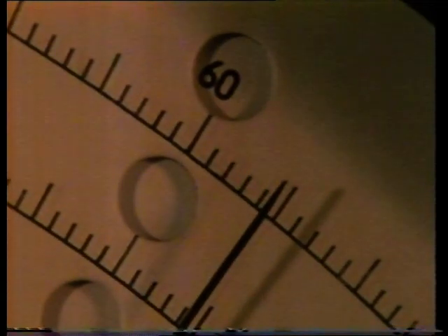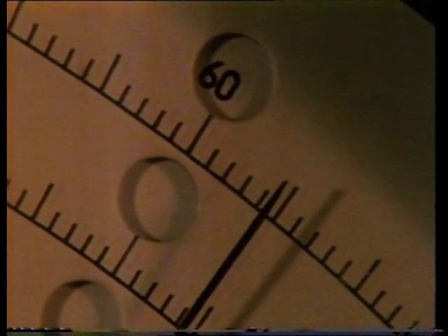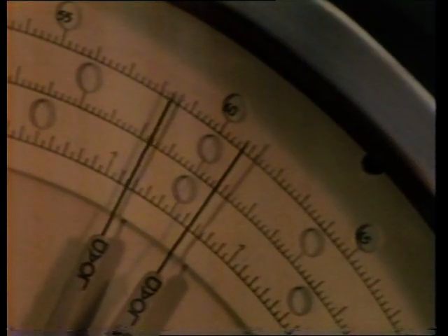Well, let's find out. What we're measuring here is the force required to pull apart a piece of 0.1% carbon steel. We're measuring the force in kilonewtons. That fractured at 61 kilonewtons. 0.25% carbon steel. Let's see what force is needed to pull this one apart. This test piece has the same dimensions as the previous one, so by comparing forces, we can compare the tensile strength.